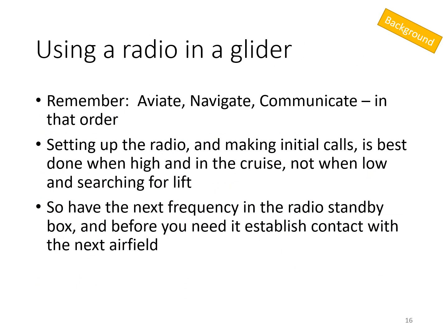Using the radio in a glider. Remember, aviate, navigate, communicate in that order. Setting up the radio and making initial calls is best done when high and in the cruise, not when you're low and searching for lift. So have the next frequency in the radio standby box, and before you need it, establish contact with the next airfield.